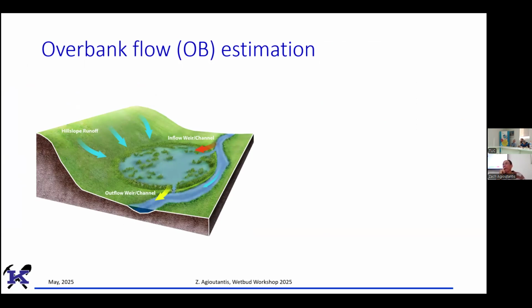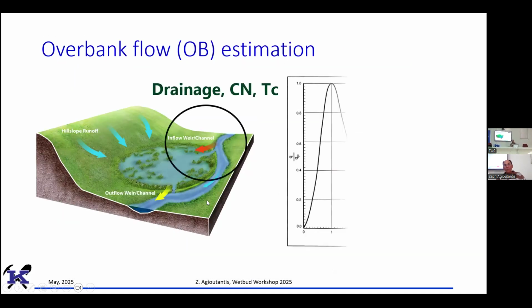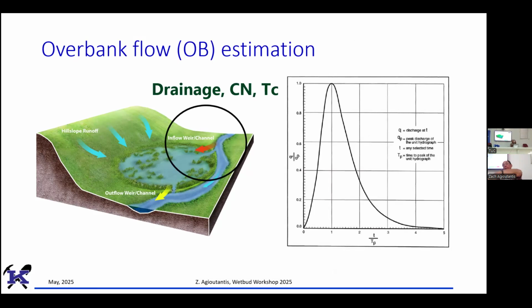What about the depth? Let's say in the lake it's like 1 meter, 1.5. Is this something that WetBud will take as a problem because of the depth? Should it always be shallow? So WetBud will need the average bottom elevation. If the bottom from the surface is 1 meter, this is actually regulated by the weir. So if you lower your weir, your gate, then you can drain the water. It will have a steeper bank, lower, but you can drain. So you can control the depth from the weir.